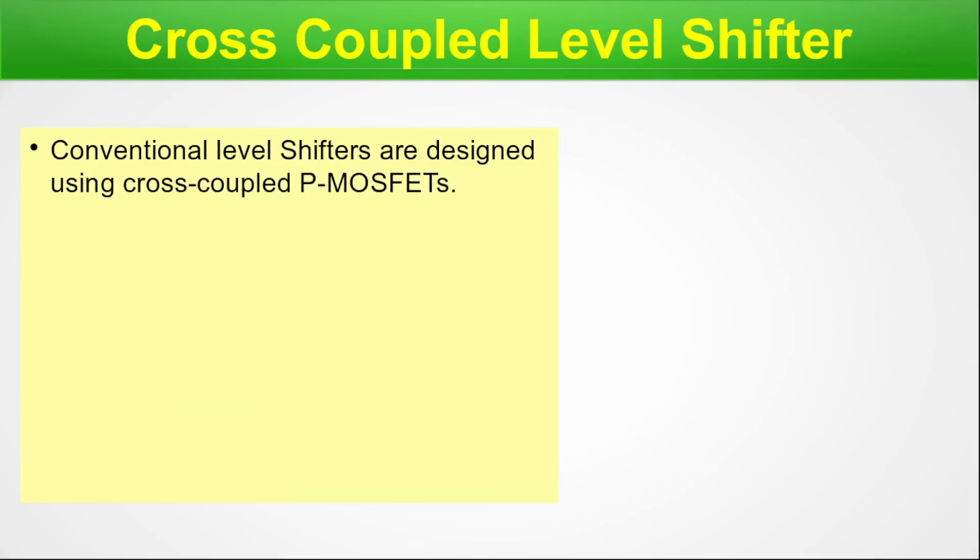Cross-coupled level shifter. So far, we have discussed the different theoretical backgrounds and physical needs of a chip of having a level shifter for clock domain crossings or voltage domain crossings. Now, in this slide, we will talk about the cross-coupled level shifter, which is an advanced level shifter in modern-day IC technology. Conventional level shifters are designed using cross-coupled PMOSFETs.